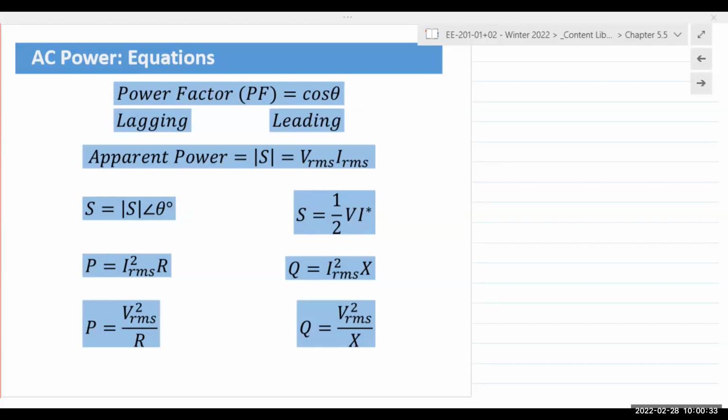Again, power factor, as I said, it's leading or lagging. And the way we bring this down is by connecting a capacitor in parallel with that inductor. So when the switch is first flipped on, the inductor receives the power in the first half cycle. It reaches a steady state. And when the power flows out, it now flows into that local capacitor.